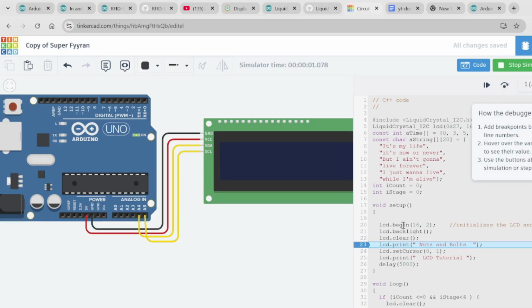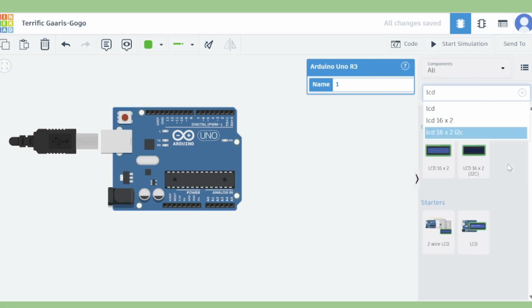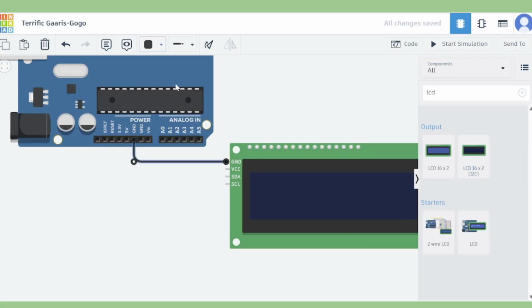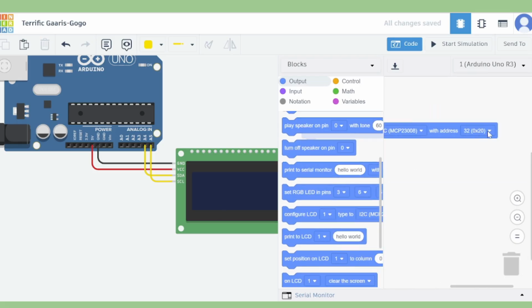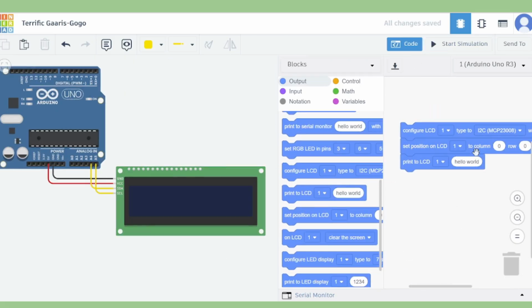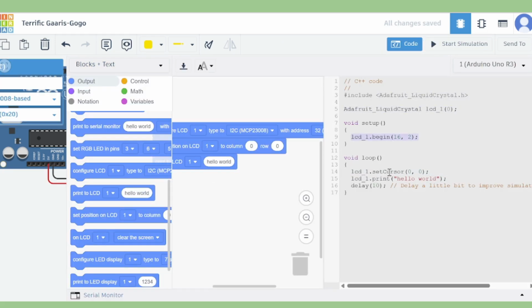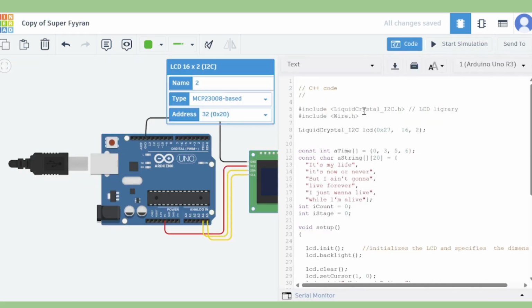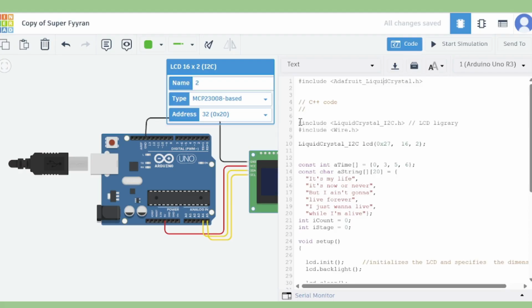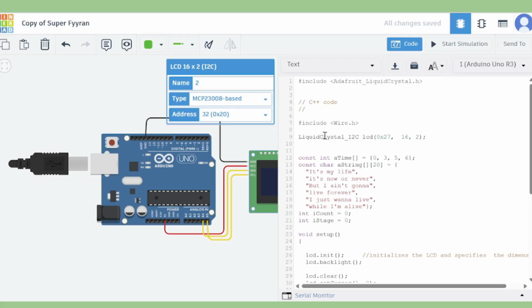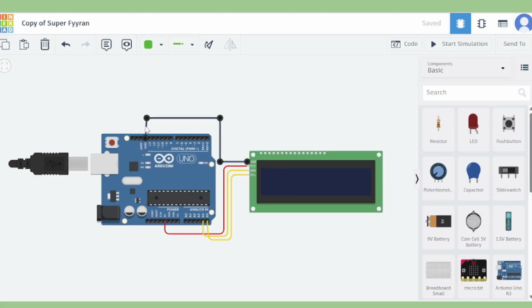any LCD examples. Luckily, I found someone who activated the LCD I2C using block mode. Following the method introduced in the tutorial, I created the block and successfully tested it. I then discovered that it uses Adafruit_LiquidCrystal. So, I replaced the previously used LiquidCrystal_I2C with Adafruit_LiquidCrystal, and it finally displayed successfully.